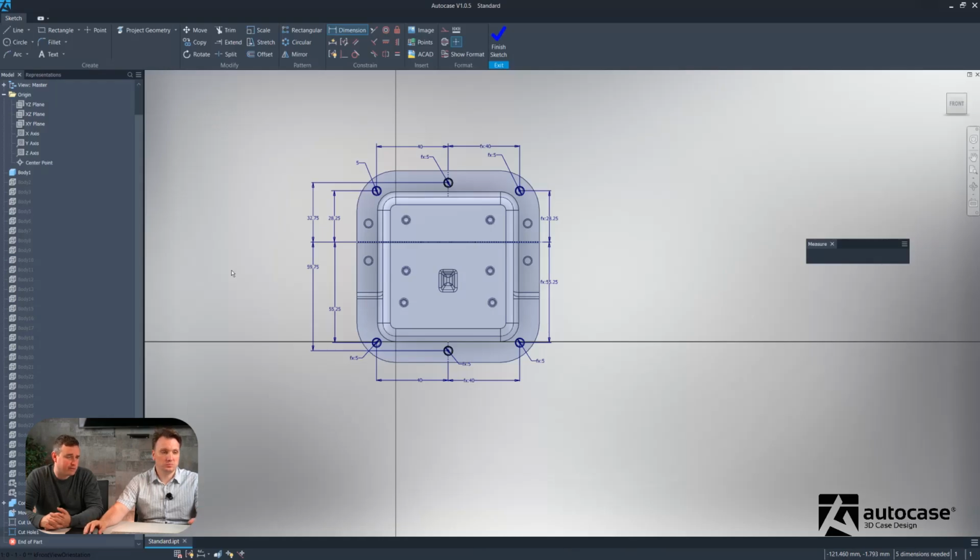The only thing we haven't dimensioned, which you can but we won't, is the middle hole should obviously be center, and it currently is. So if for whatever reason it wasn't, you could control the position of the middle hole by referencing that, but we don't need to because it's essentially 0mm offset.